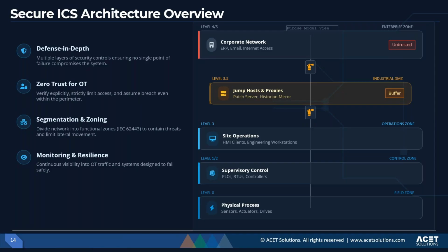the control devices. And finally, continuous monitoring provides real-time visibility using tools such as the SIEM platform, OT-specific anomaly detection systems, and log collectors. These systems might detect unusual write commands to the PLC or unexpected firmware changes. So altogether, these controls create a robust ICS security architecture capable of meeting modern cyber threats while supporting stable and reliable industrial operations. We will go through these principles in detail later in the session.